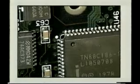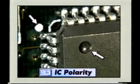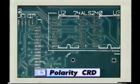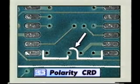All ICs have polarity, so placing them on the board correctly is very important. It's not a negative or positive lead you'll be looking for with an IC. Instead, a dot or notch will mark the number 1 lead. A matching mark on the board will show how to align the IC.